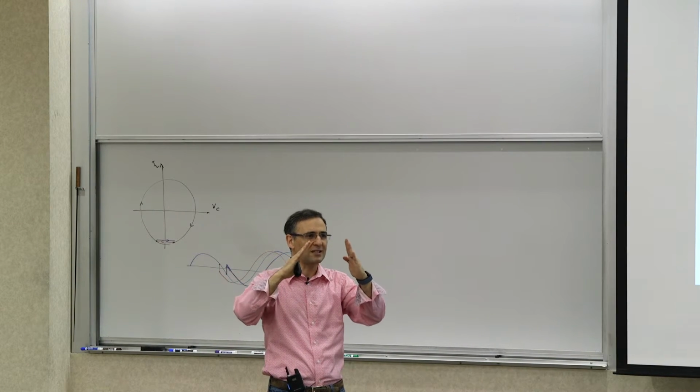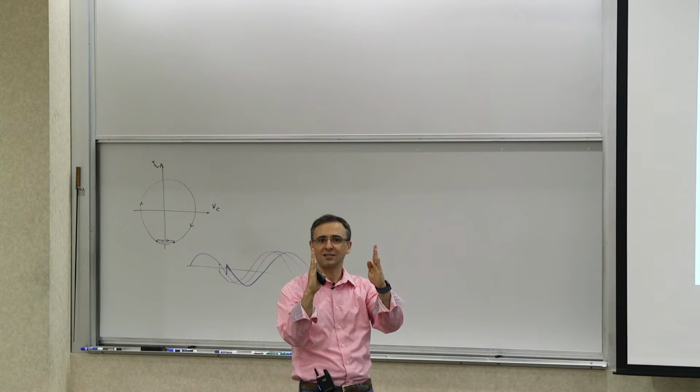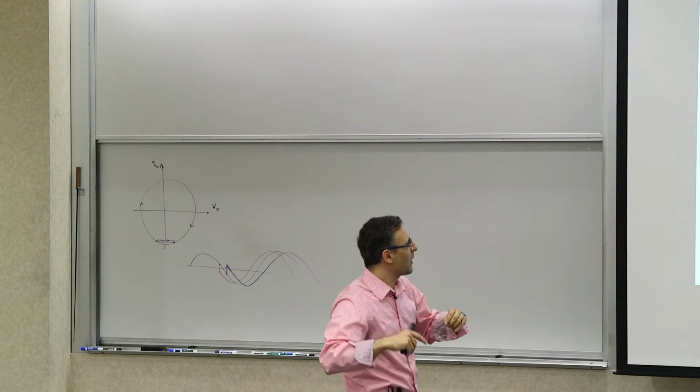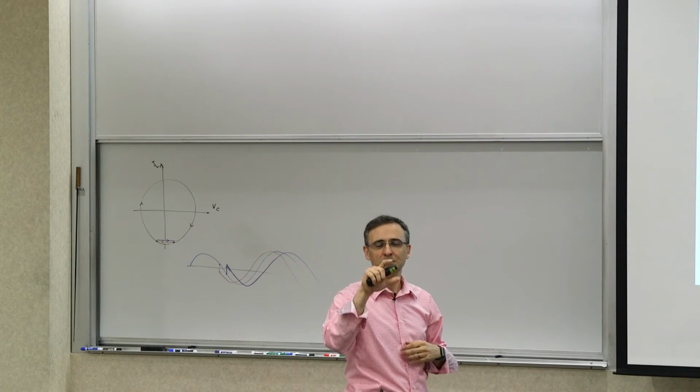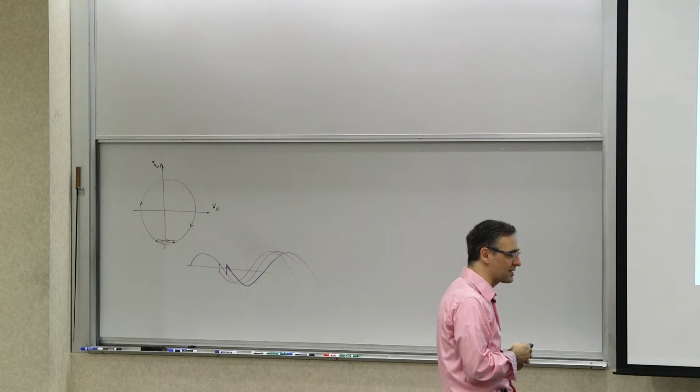If you look at a 15-stage ring oscillator, the transitions have to be faster, right? Because otherwise you would not get the same frequency of oscillation out of 15 stages versus 3 stages. Which means that you have sharper edges, which means that the lobes of the ISF will be shorter and thinner, as you can actually see in this example.